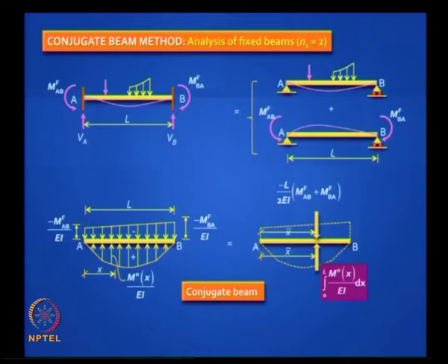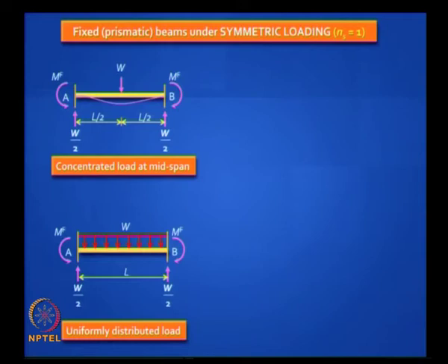And what is interesting here is that if you equate the two areas, you will find that the bottom area is integral 0 to L M0x dx by EI, and there are some advantages you get when the loading is symmetric. So let us look at those special cases where you have symmetric loading.